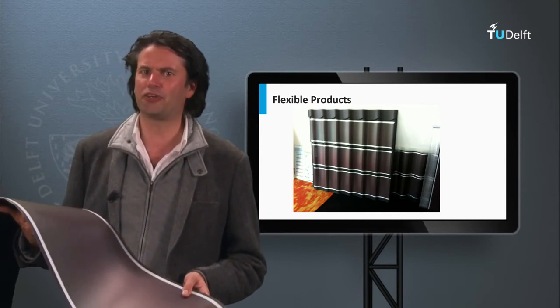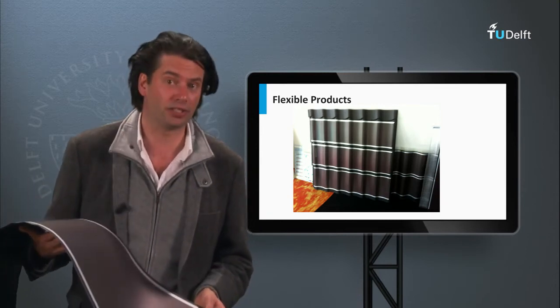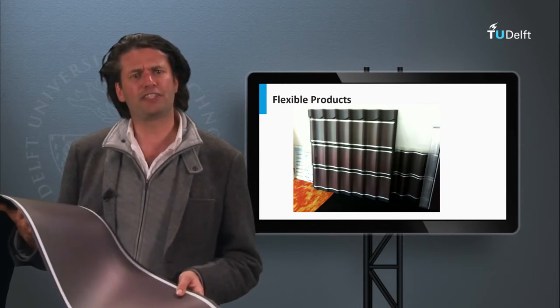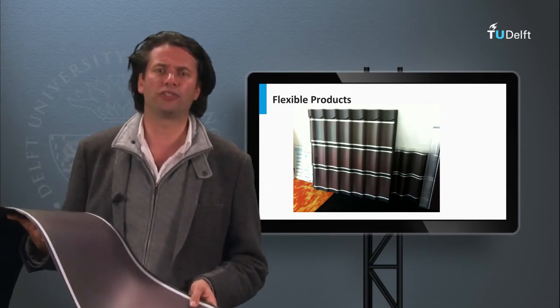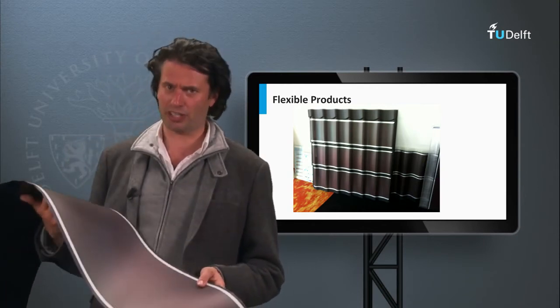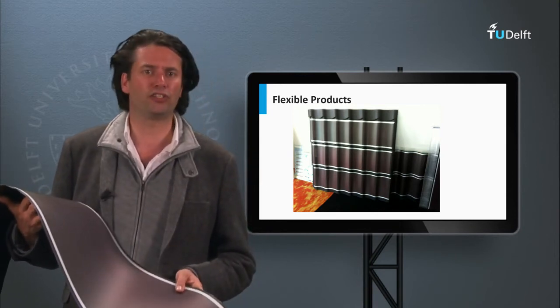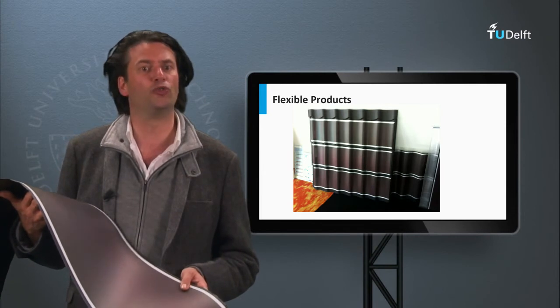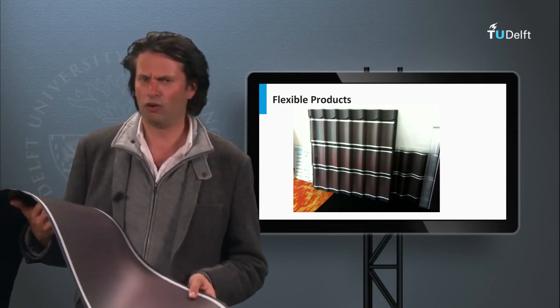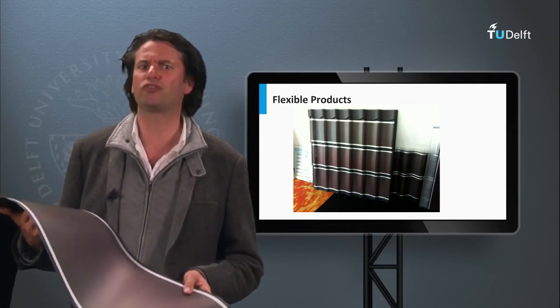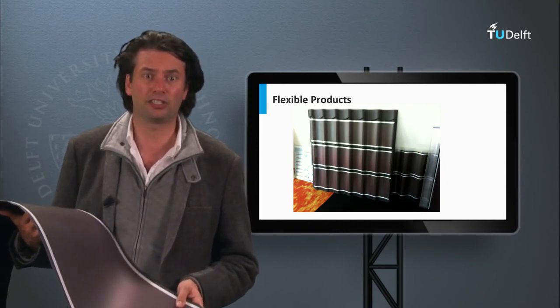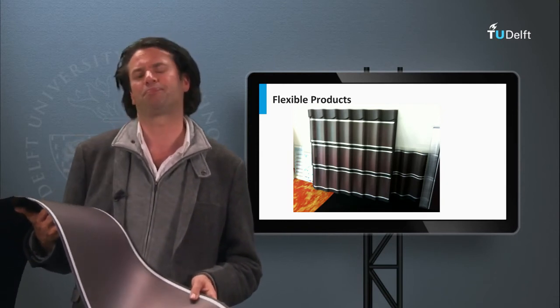This was the quick introduction into thin film silicon PV technology. In view of time limitation, I did not talk about the thin film silicon junction crystalline solar cells. These are based on thermal crystallization of amorphous silicon deposited on non-wafer based substrates. On lab scale, close to 12% conversion efficiencies have been achieved with this approach as well.